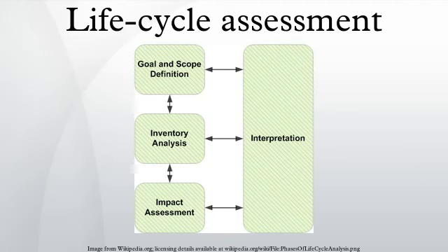The well-to-wheel variant has a significant input on a model developed by the Argonne National Laboratory. The greenhouse gases, regulated emissions, and energy use in transportation model was developed to evaluate the impacts of new fuels and vehicle technologies. The model evaluates the impacts of fuel use using a well-to-wheel evaluation, while a traditional cradle-to-grave approach is used to determine the impacts from the vehicle itself. The model reports energy use, greenhouse gas emissions, and 6 additional pollutants: volatile organic compounds, carbon monoxide, nitrogen oxide, particulate matter with size smaller than 10 micrometer, particulate matter with size smaller than 2.5 micrometer, and sulfur oxides.